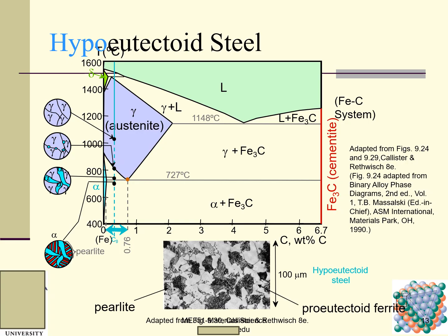And the micrograph shows this one. So this is pearlite. This larger white one here, we call pro-eutectoid ferrite. Here it corresponds to this one. If I give you this micrograph and ask you to label these different phases, can you do that? I hope you can. Next slide.